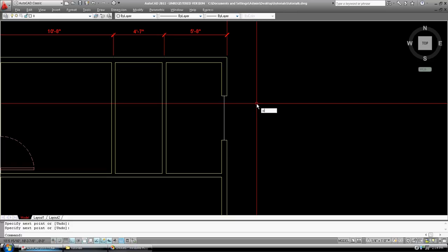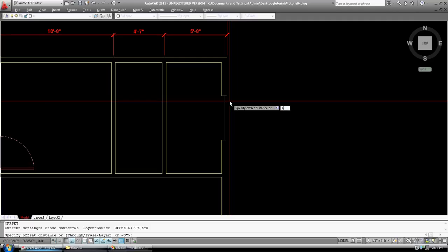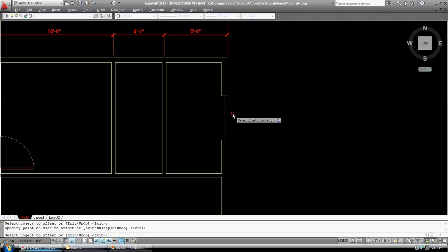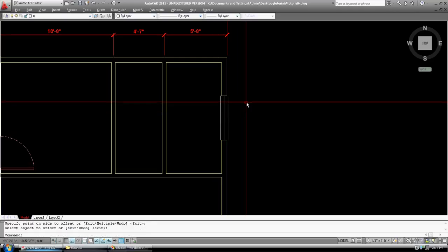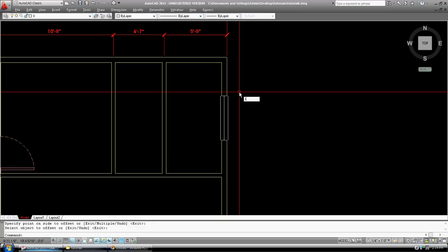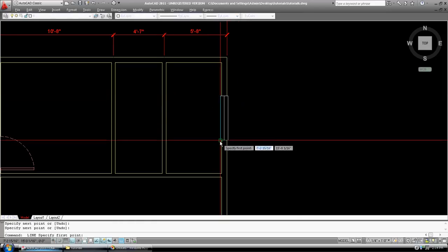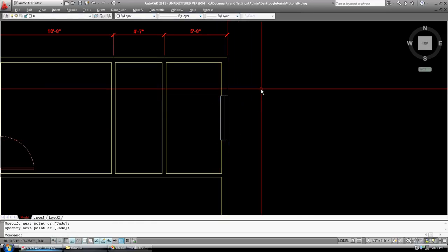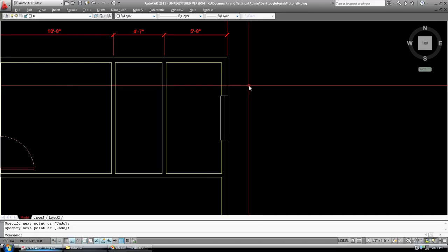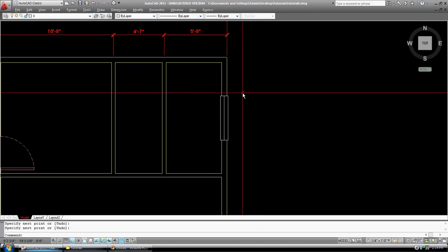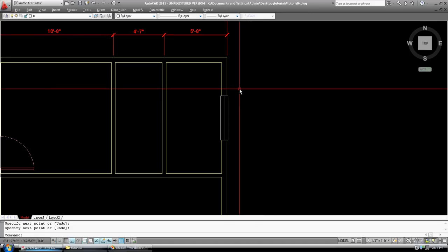You can offset instead of 3 inches, 4 inches. Okay, so now you're sticking out an inch from the wall, and you can draw a line from there to there and there to there. Okay, so that might be a good window block. I like the center line because eventually I'll turn that into a beam.